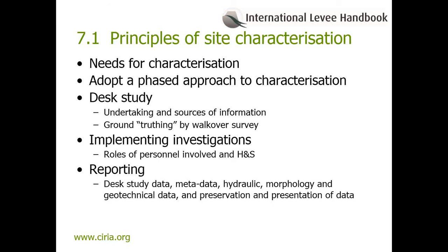Characterization of the hydraulics encompasses the collection of information about the movement of surface water with the aim of developing models that represent physical processes. Characterization of the geotechnics involves defining the spatial distribution and properties of the soil forming the levee and the foundations, and assessing the existing groundwater regime. It may also include unexploded ordnance, contamination, archaeology, but consideration of these is beyond the scope of the ILH, and specialist advice should be sought.